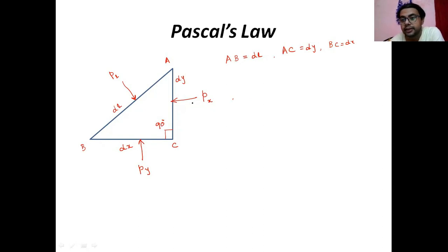Now, what is the force acting? Pressure is a time average force per unit area. So if you multiply the pressure with the area, you will get the force. Here the force is Px into dy, taking unit length perpendicular to the plane, so into 1. Here Py into dx into 1.